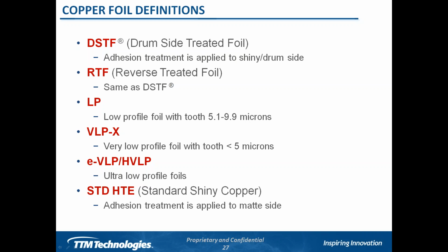So as foil manufacturers realize that the foil has to be smoother in high speed and high frequency applications, they're trying to get these things as smooth as possible, but also still be able to bond them onto the laminate that they're supplying, because at the end of the day, there still is a peel strength value that we have to meet as fabricators to ensure that the copper doesn't just come right off, let's say after assembly, for example. And then as we increase in terms of quality of foil, the foil roughness also starts to become a lot thinner.